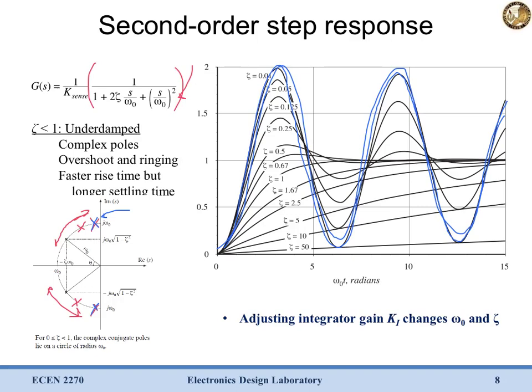As we start to move these poles down, as we start to increase the real part of them and move them closer to the real axis, and further away from this imaginary one, we can start to reduce the magnitude of this ringing and have our system settle to its desired reference value faster and faster.